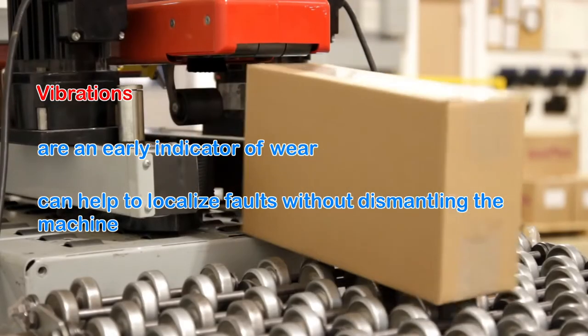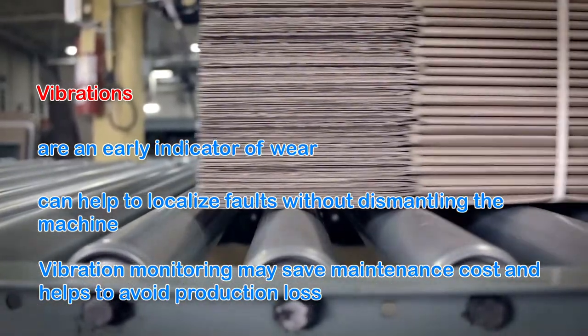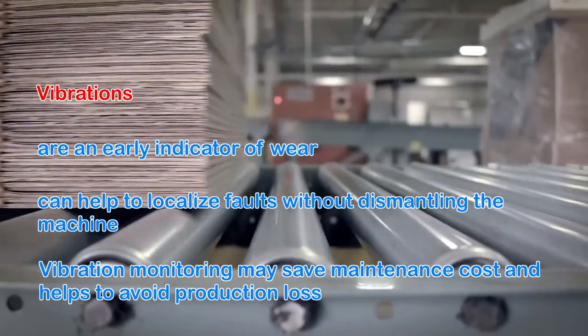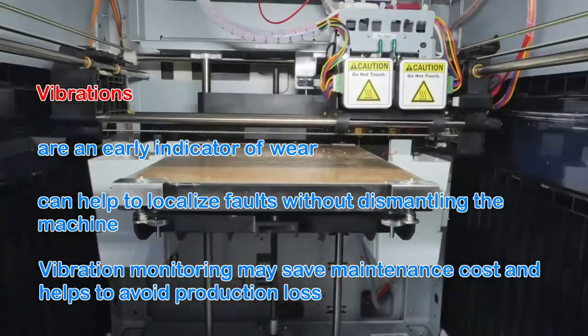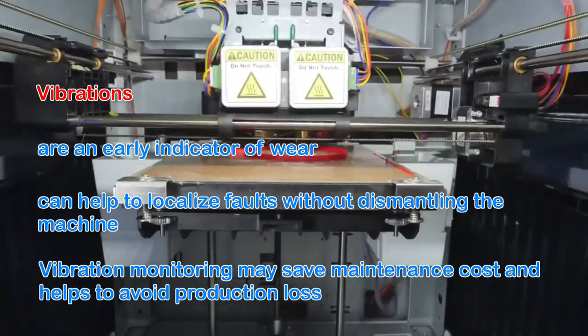Permanent vibration monitoring helps to detect emerging problems. When the vibration magnitude is slowly rising, maintenance can be scheduled before it comes to breakdown. This may help to save maintenance cost, and to avoid production loss.